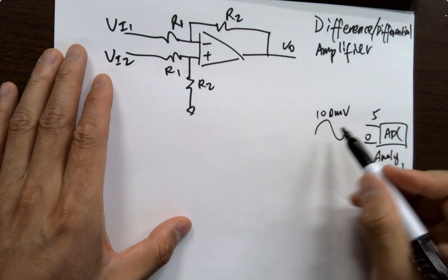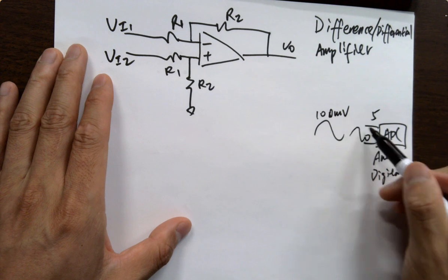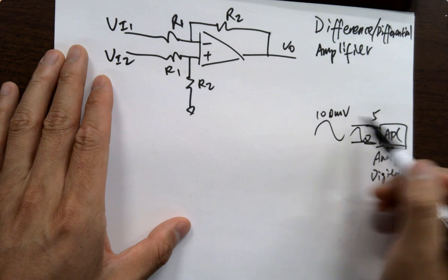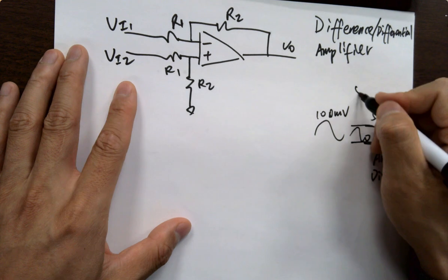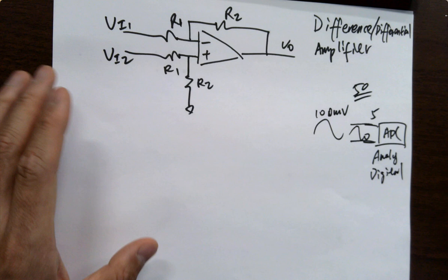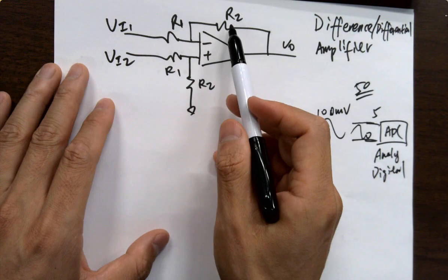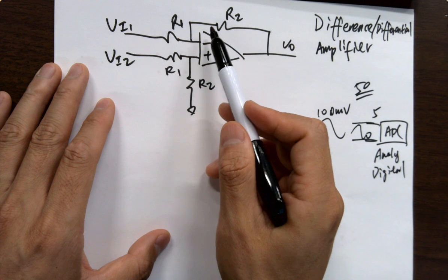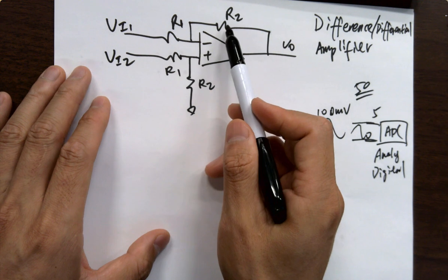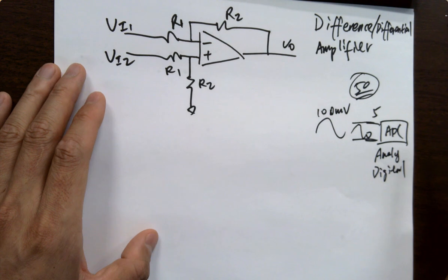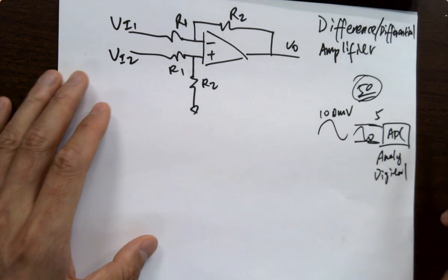So you want to amplify your signal to this range so you can use the full resolution and not lose any. From here to here, it's about 50 times, some estimate. So that's why you need to know the resistors to find out the gain. That's the process of designing an op-amp circuit, since right now you're targeting this value, right? Okay.